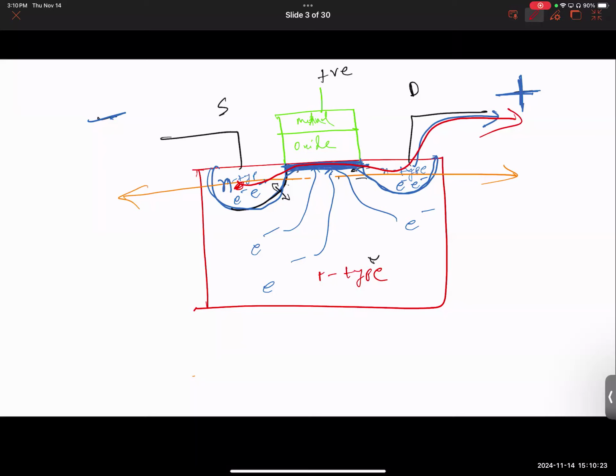See the point here? From the source, you'll have a constant flow of electrons moving towards the drain, getting out of the drain. You create that by applying a positive voltage. Now, the moment you remove that positive voltage, what happens? This inversion layer is gone, and you have back-to-back diodes again and no flow. So it goes from being on, where current is flowing, to off, no current flowing. Very simple concept, don't you think?